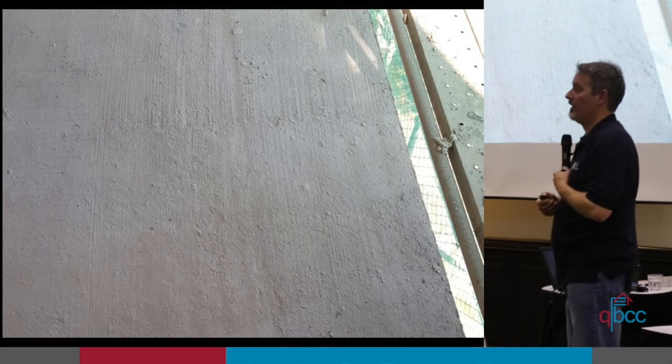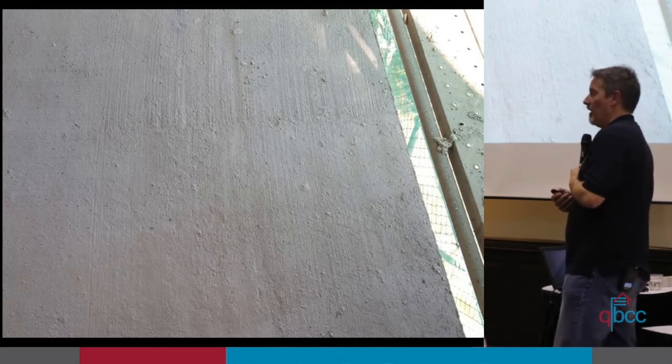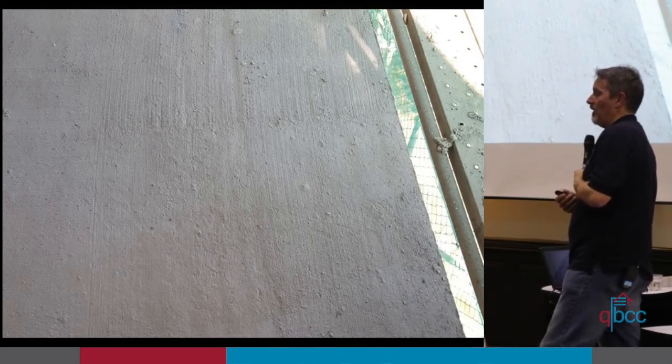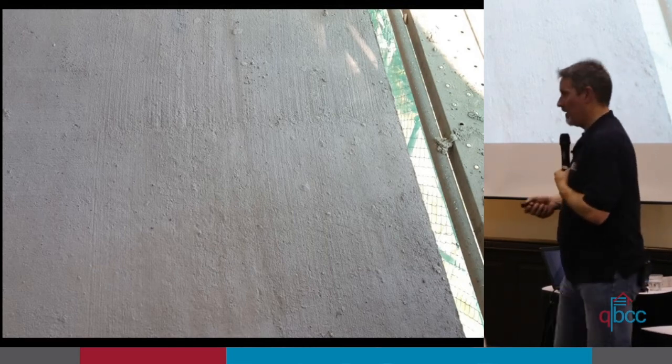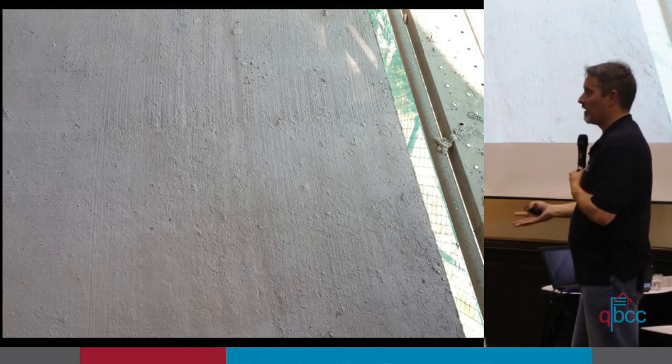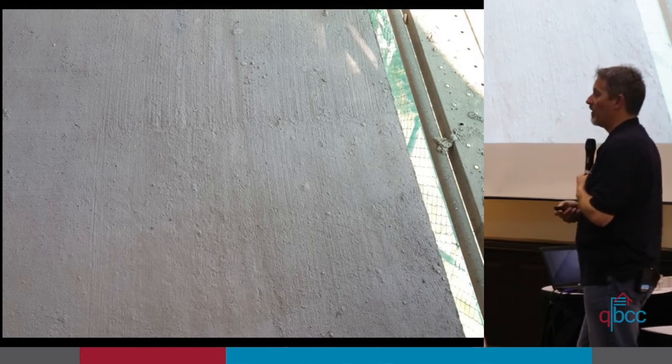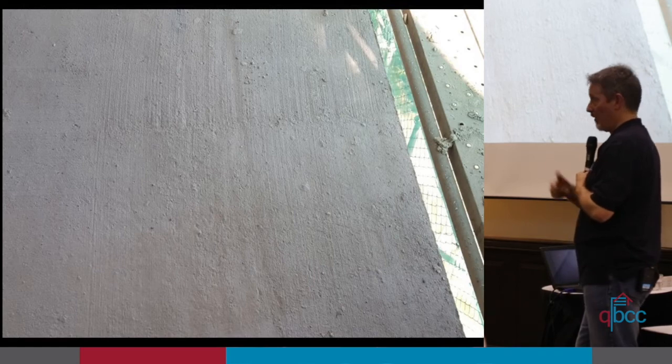Neither is that. Yes, that's broom finish, but it's actually too heavy. Right? So if you've ever walked across something like that and just twisted your feet a little bit, you can actually rub the top surface of the concrete off, and broom finish like that is way too soft for a membrane or even direct fixing tiles.